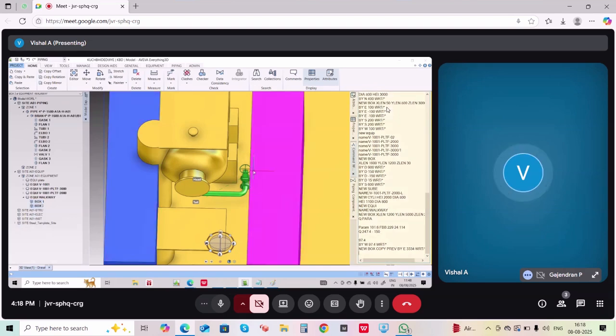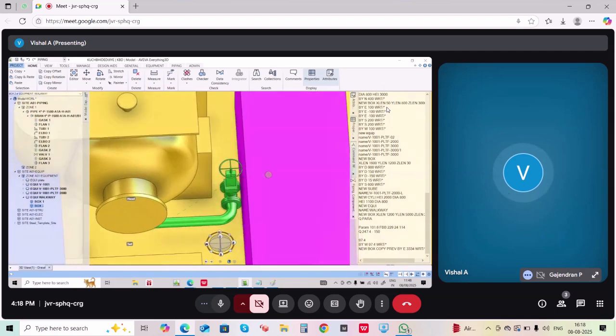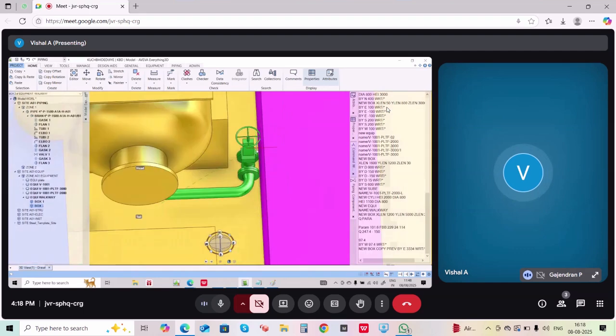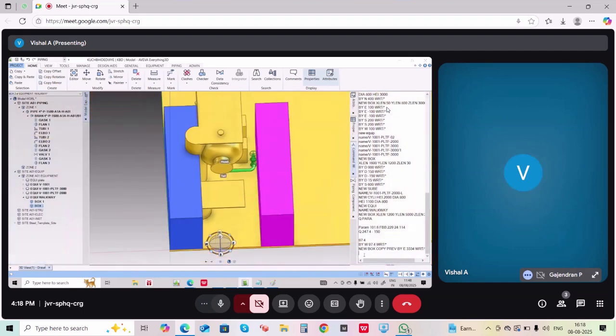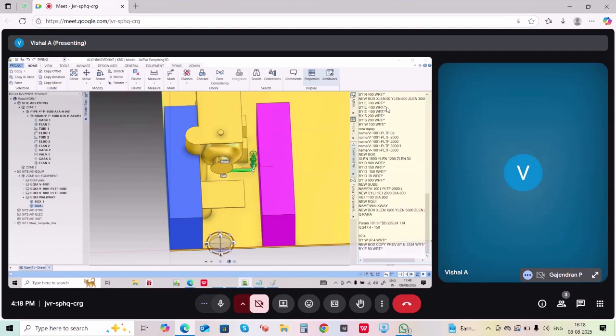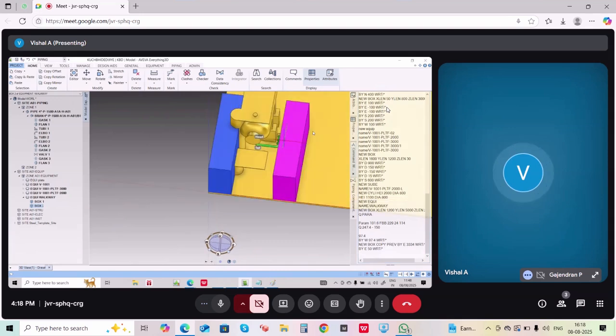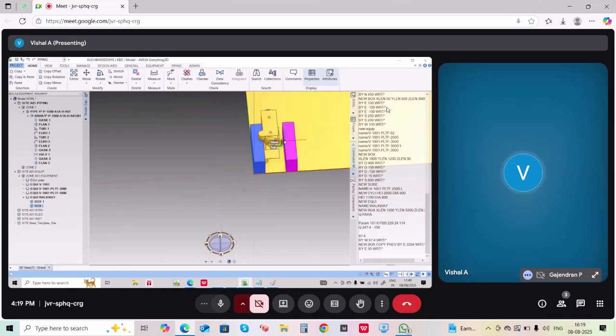So I have a walkway here, and it's slightly clashing because it is coming from the center of this. So you can move it a little bit, 50 towards east, by east 50 WRT slash star, enter. So this is how you create a walkway when you do piping here. Now if you have any other equipment here, then again the piping will go like this, and then the equipment will be here. You got my mind? So this is how